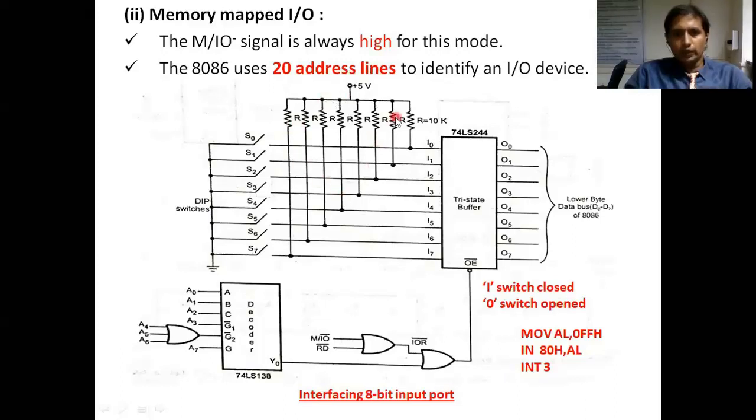Okay, in order to control the current, we use resistance with voltage. And what is the resistance value? 10 kilo ohm. For example, voltage is 5 volts, means what is the maximum allowable current here? 5 volts divided by resistance, nothing but 5 divided by 10k. Okay, that much current only it can allow maximum. For that case we use this arrangement.